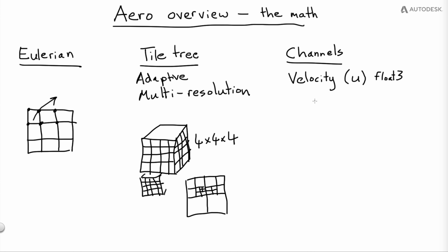And this is actually worth mentioning. Unlike some fluid solvers, we actually store this as 3-dimensional vectors sampled at grid cell corners, which would seem to be the obvious thing, right? There are a lot of fluid solvers out there which use a different arrangement, a staggered grid arrangement, or sometimes it's called a MAC grid, where they split up the different components and store them in different locations.